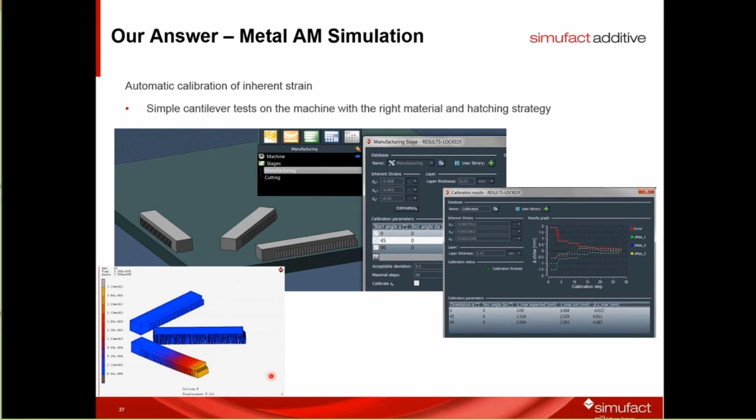Then when you build other parts in the same hardware configuration, those inherent strains can work again. If you want to use a different powder or a different power, you need to recalibrate and recalculate those inherent strains, and then Simufact Additive will form a database of all your different inherent strain values.